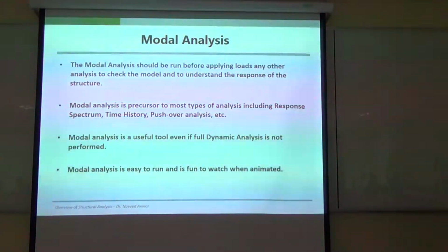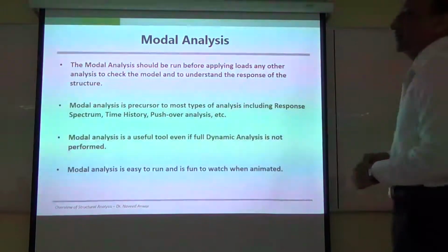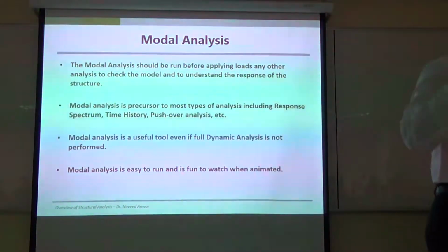Just one mistake. But had he run the modal analysis, he would have known that there is a mistake in the density, because natural period would have been wrong. And if he knew how to read natural periods, he would have immediately known something is wrong. But he didn't. And it led to foundation design and everything being so heavy, because everything is made from steel, not concrete. Right?